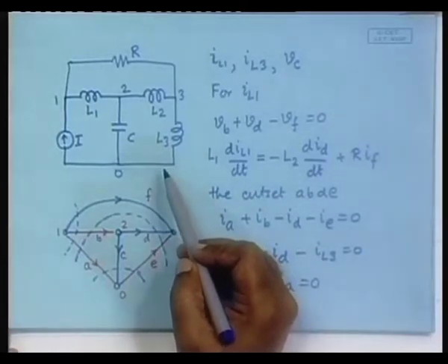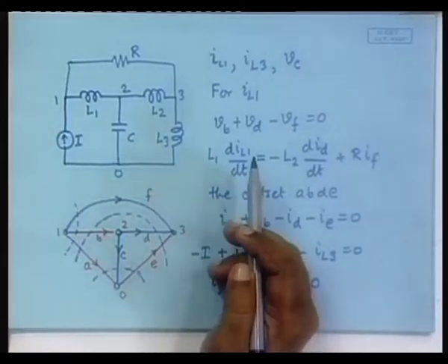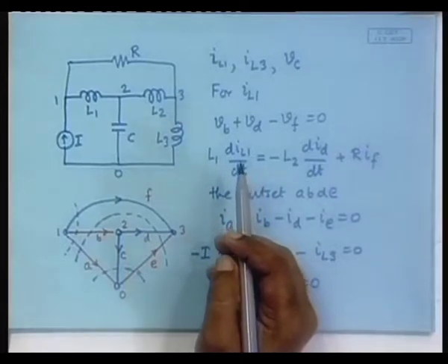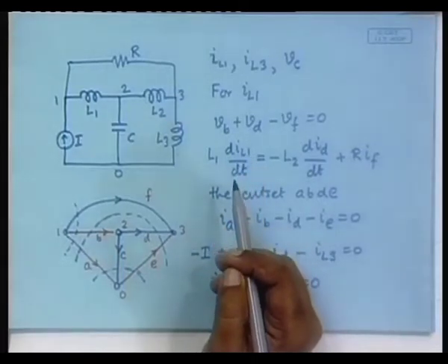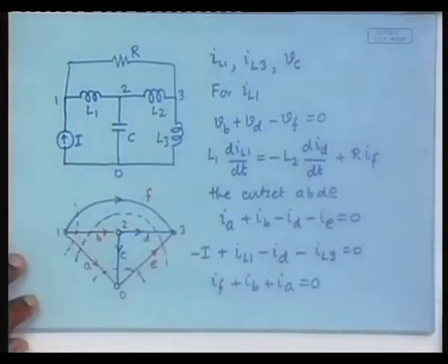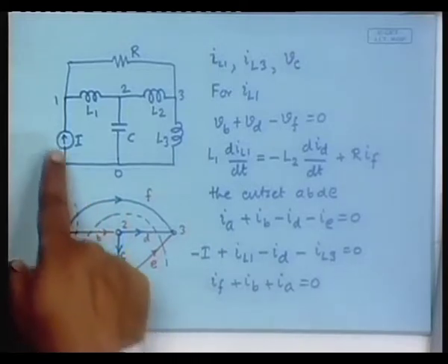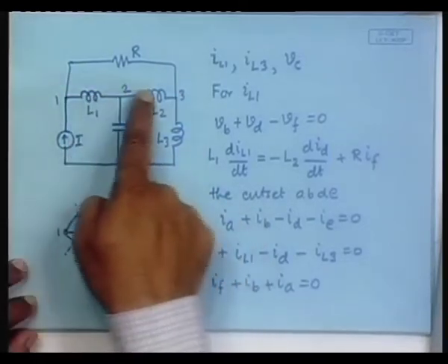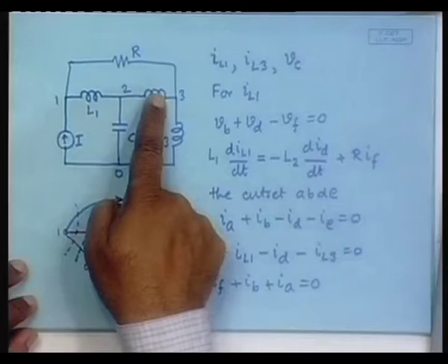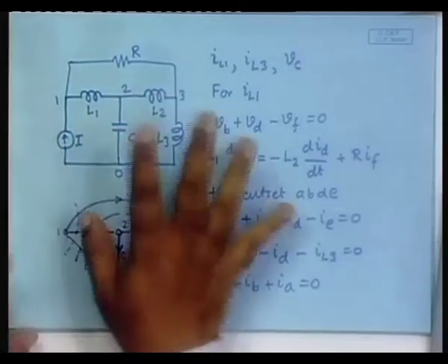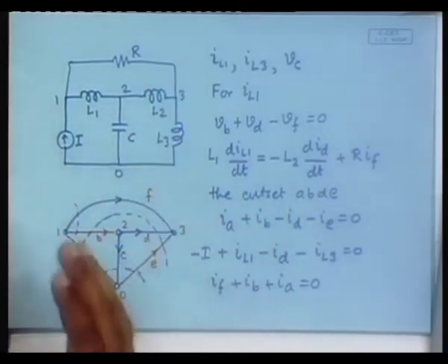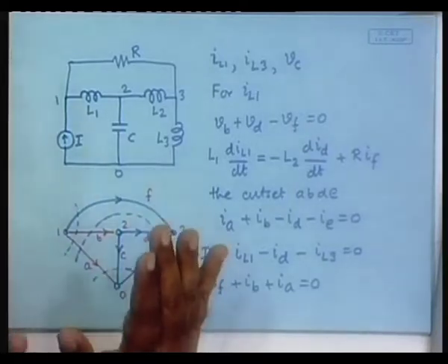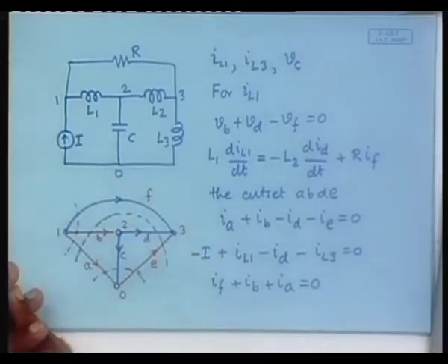Now, why did this problem happen? Can you identify why this problem happened? Yes, something forms that contains only the current source and the inductors, this loop, current source and the inductors. Therefore, all the currents in the inductors cannot remain independent variables, and whenever that happens, there is a practical circuit problem, and you should understand that you should never connect a circuit like that.